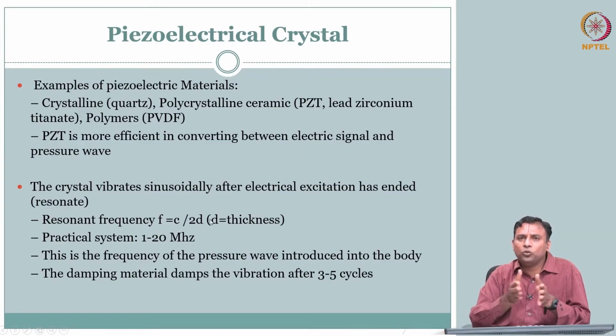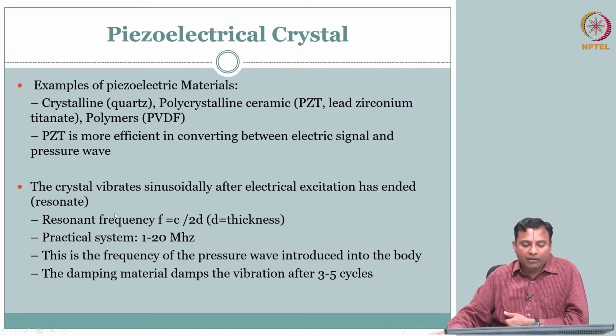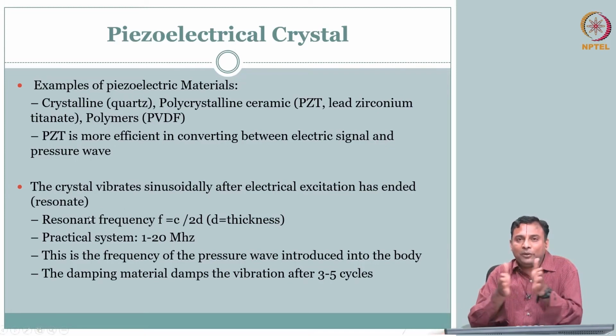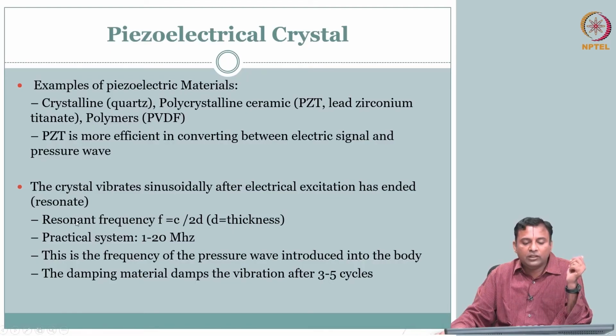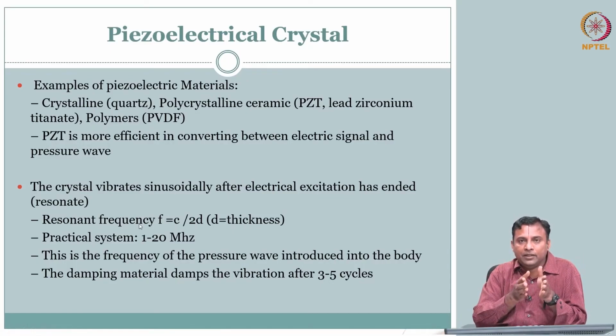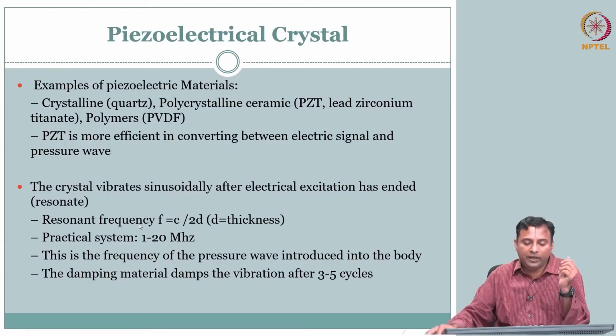Of course, this has to do with the mode of propagation, the crystal, the stress strain of this crystal, all of which we are not really going into in depth. Okay. So, we have engineered this crystal predominantly to vibrate in only one mode, which is your thickness mode, and therefore, your resonant frequency can be specified by changing the thickness of the crystal.